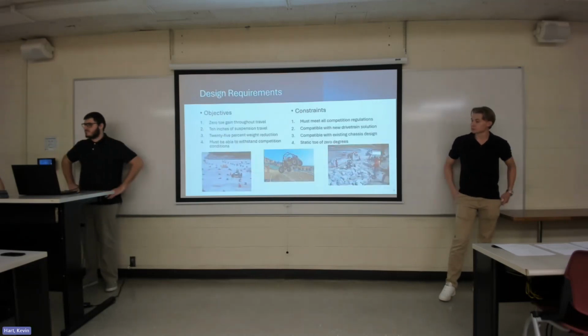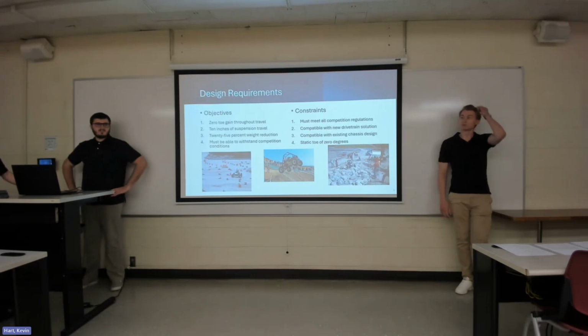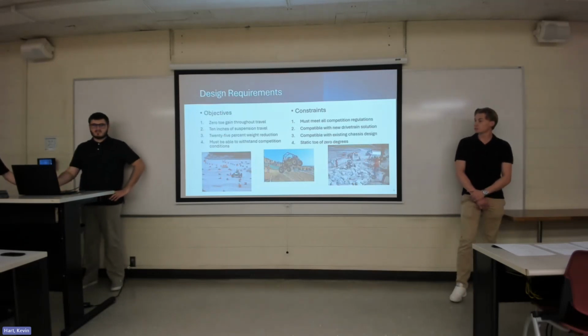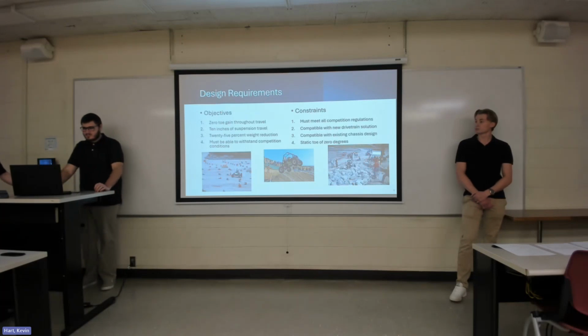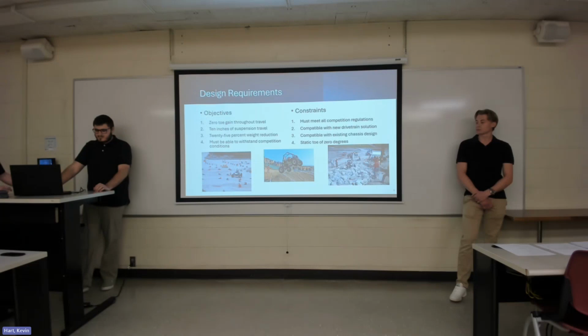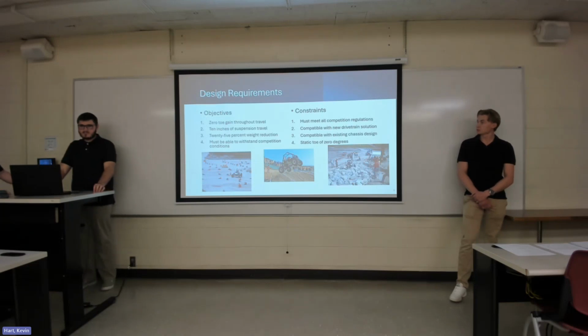Yeah, so with this project, we had some objectives and constraints. Our objectives included having 0 toe gain throughout the suspension travel. We also wanted at least 10 inches of suspension travel, at least a 25% weight reduction compared to the previous Big Red rear suspension. And then we wanted to have it withstand competition conditions, like rough terrain that we'll have to go over very quickly, which would be very hard on the suspension.